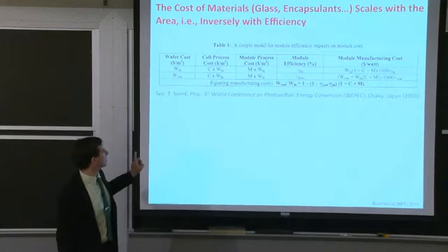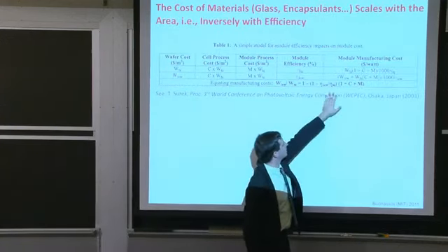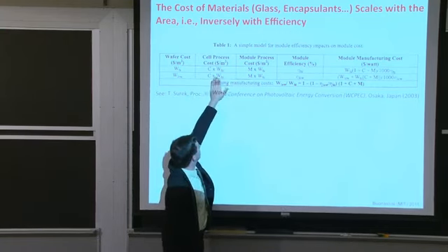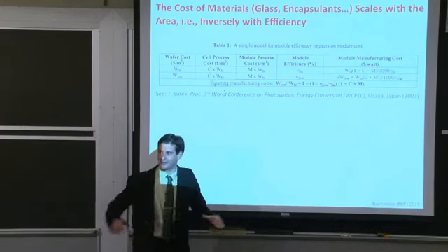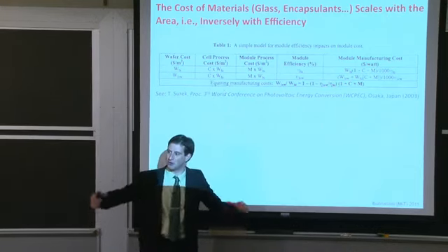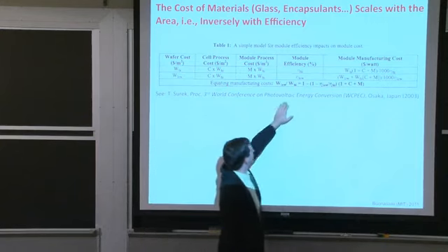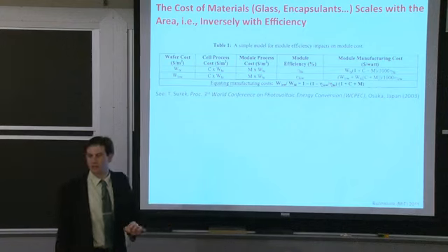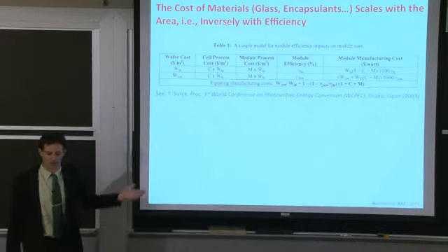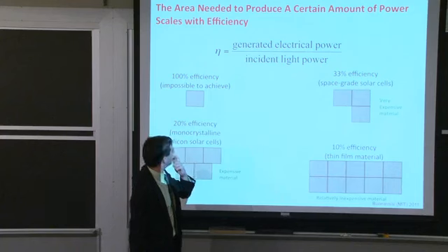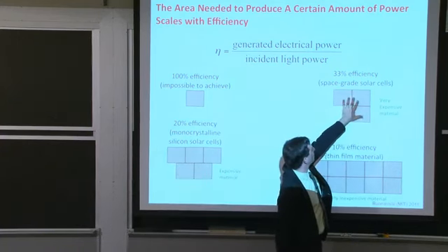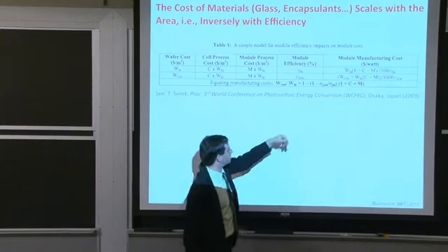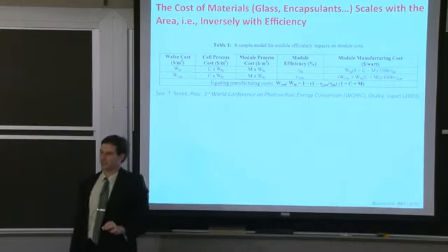And so a simple equation that calculates all these parameters in, the material costs, the module efficiency, essentially the material and wafer costs are being calculated in dollars per meter squared. They're saying how many dollars go into producing a meter squared of this material. And the efficiency is over here, and this is just a very simple back of the envelope calculation type of way of estimating the cost of a solar system. So if you say, okay, I'm willing to pay more for a higher efficiency cell because I'm using less area, you can use this type of calculation to get to the answer quickly.